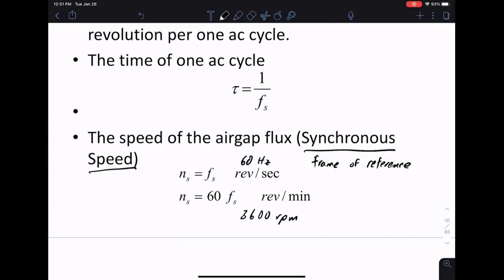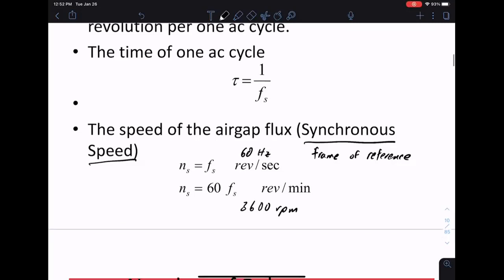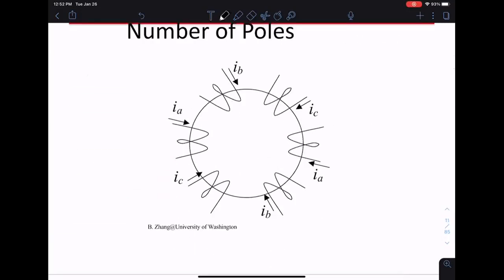Okay, so imagine what the normal turning rate for wind turbine blades is. Those are nowhere close to 60 hertz. Even wind turbines in very high wind do not turn anywhere close to this. If your synchronous speed is 3600 RPM and all you're doing is relying on your gearbox to shift to this kind of speed, that's very hard, not trivial. The idea is we can slow down the synchronous speed, and the way to slow down synchronous speed is to add poles, add a number of poles.